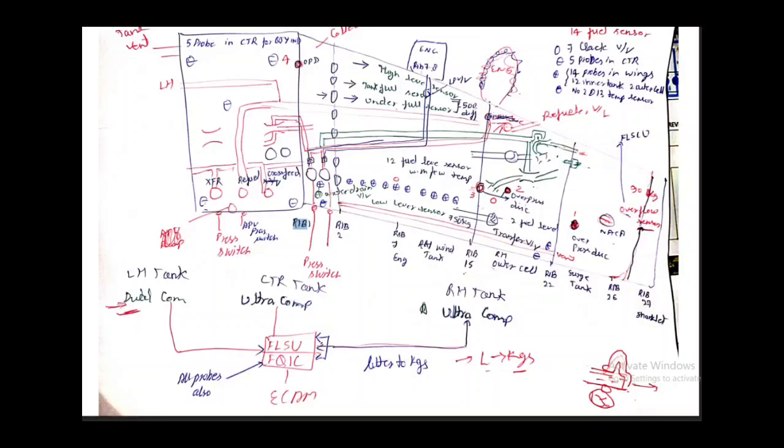Why is this there? You will see there is a tank, the wing tank. There are 2 pumps, pump 1 and pump 2. These pumps come between rib 1 and rib 2, and here you will get the pressure switch also. You can see from the landing gear area there are 2 pressure switches behind the wing area. So, for example, once you are on the ground, everything is good, fuel is going perfectly, the aircraft is running, the APU is running, engine start is also good, because you are stable on the ground.